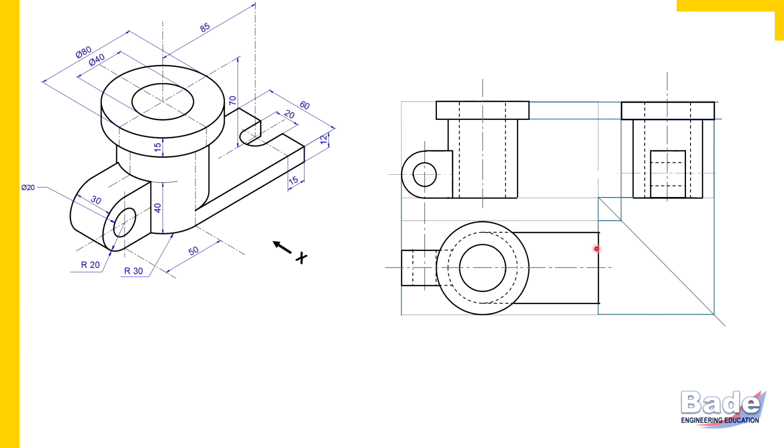So draw end projectors, the right end of the plate and the left end of the plate. Now the left end of the plate is where that plate meets the cylindrical surface. So here. From this point where right now this red spot is, and this point we should draw end projectors. So these are the end projectors. This is the base plate of height 12 millimeters.